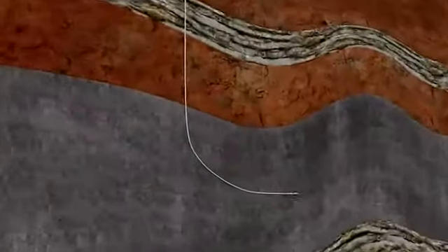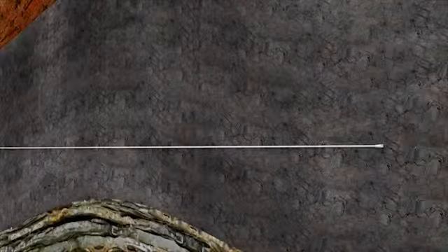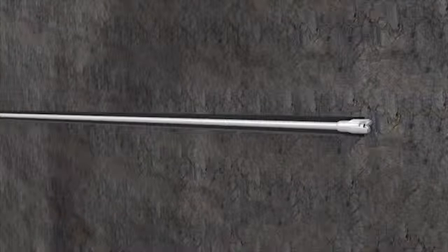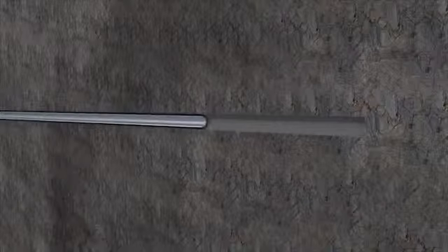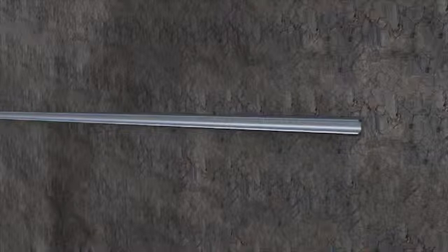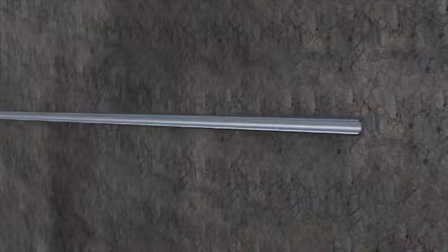One of the advantages of horizontal drilling is that it's possible to drill several wells from only one drilling pad, minimizing the impact to the surface environment. When the targeted distance is reached, the drill pipe is removed, and additional steel casing is inserted through the full length of the wellbore. Once again, the casing is cemented in place. For some horizontal developments, new technology in the form of sliding sleeves and mechanical isolation devices replace cement in the creation of isolations along the wellbore.